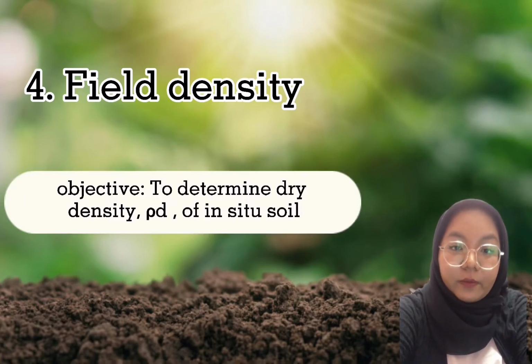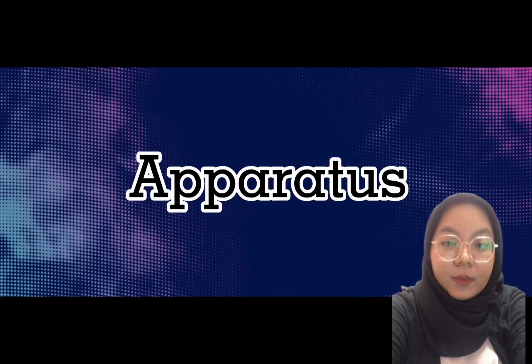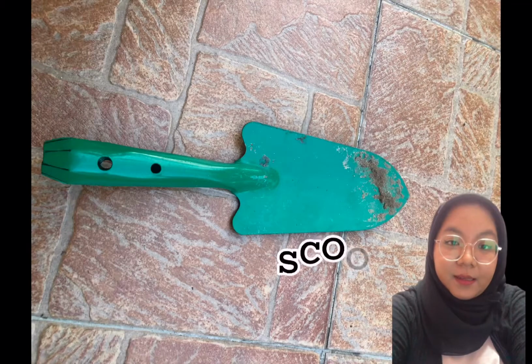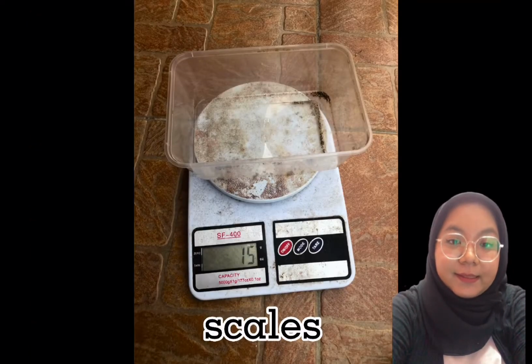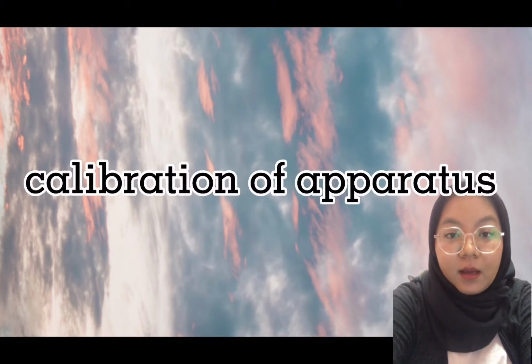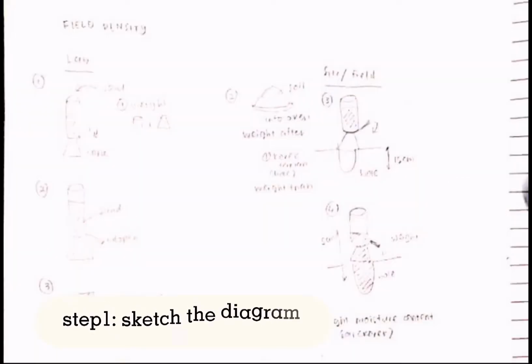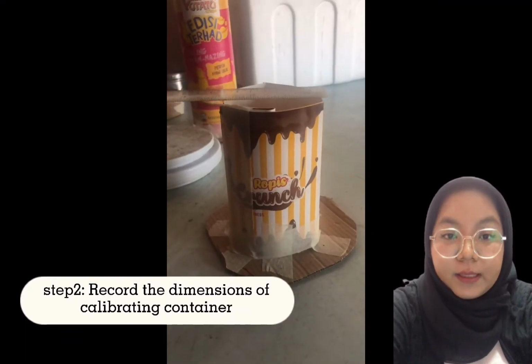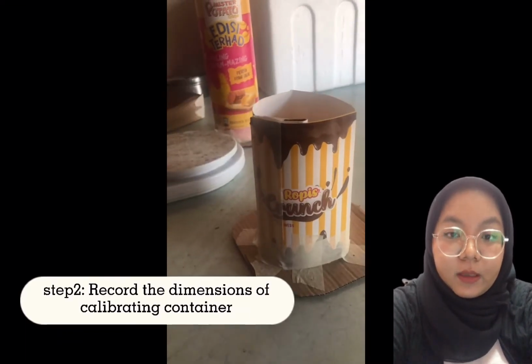The objective of the experiment is to determine the dry density of in situ soil. The apparatus that we use are the set of pouring cylinder, scale and sand. For the calibration of apparatus, record all the dimensions of the calibrating container.